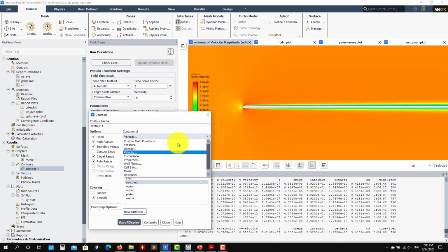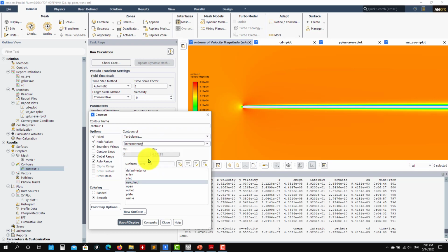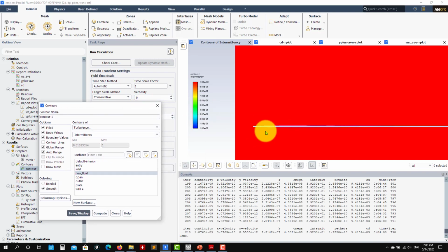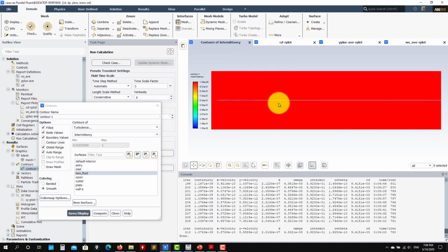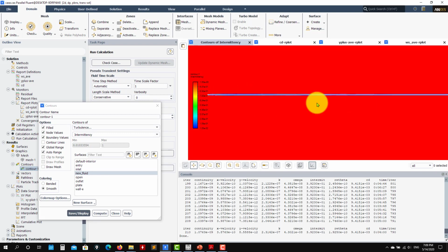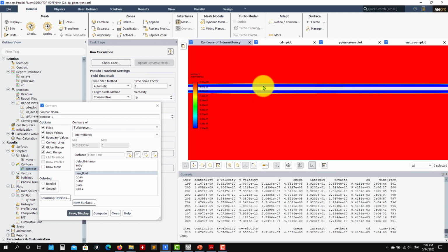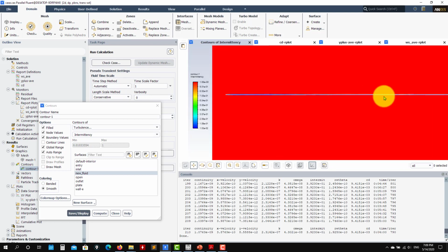But what is interesting to see here is that if you go in the turbulence tab, you will access the intermittency field. And as you plot this one, this is the one that is telling you where you have turbulent or laminar flow. So see that we define these boundary conditions where everything is turbulent, okay? And where you have the blue region, blue means laminar. So see that all this region is laminar, so it's a large boundary layer. And then you go back, you will see that